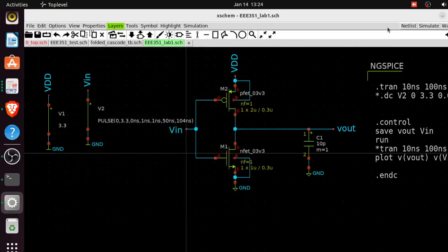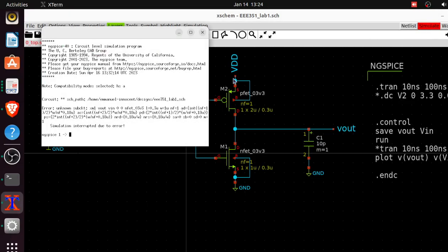So that's all. Then you're done. You click this, we've done that. Then next thing, you click on simulate. Then yes, good. So now there was no issue with our netlist, Spice netlist, as far as the whole Spice language thing is concerned.